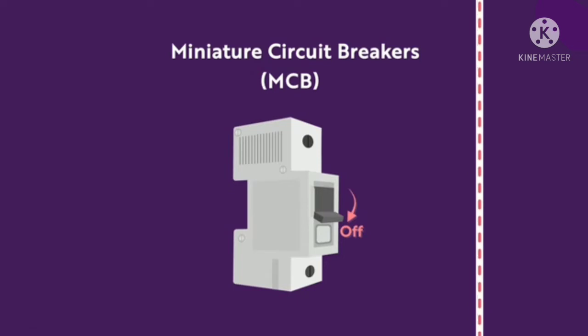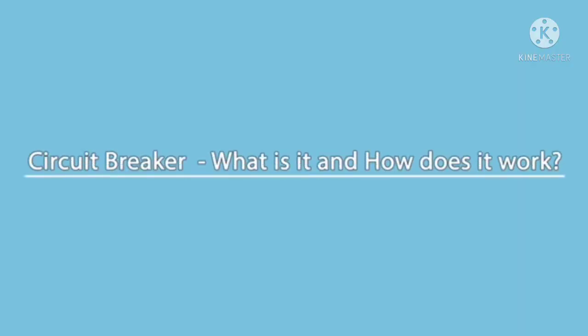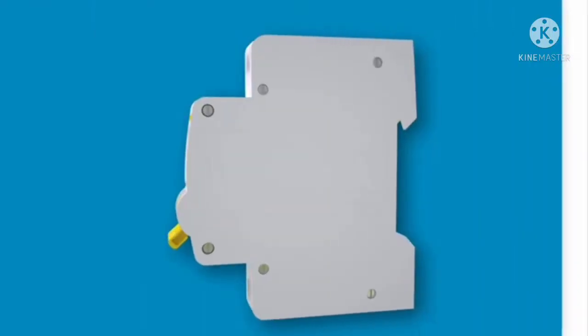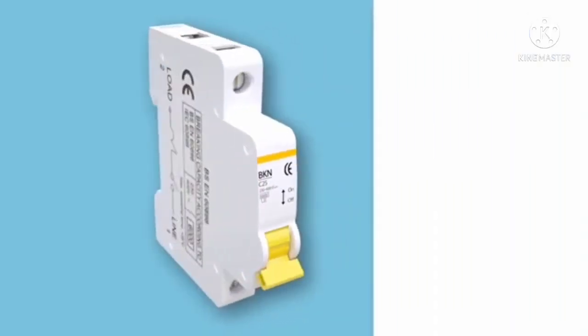Never substitute a fuse of greater capacity than that specified for a particular circuit. If the fuse has the ability to carry more current than originally designed, the wire will heat up before the fuse melts, and this could start a fire.